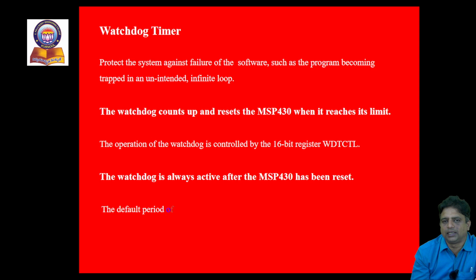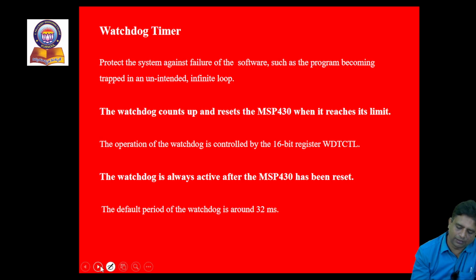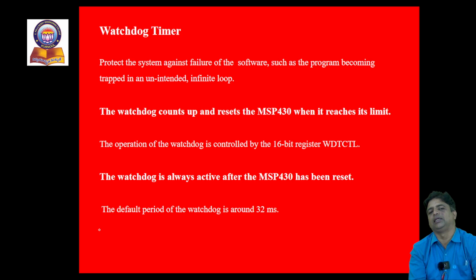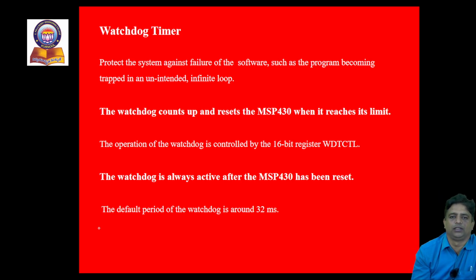If it is not getting reset, it will go to the CPU telling it that you have not come to reset me, so maybe you are inactive, kindly invoke yourself. The duration for sleeping of a CPU will be 32 milliseconds. That is the duty of this timer; its only duty is to count the sleep time for our microcontroller.